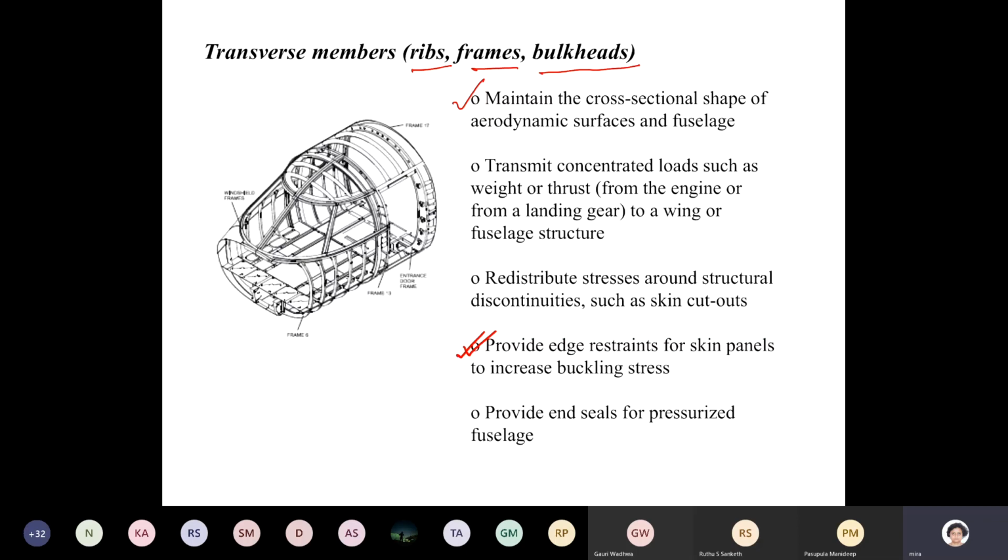That's what the bulkheads do. The mathematical part, the part that comes from stress analysis, will be done only at the end of the course when we talk about buckling. But you will be able to visualize that bulkheads are nothing but the two fixed ends of the Coke can. Those two ends resist the compression of the Coke can, and that's what bulkheads do. They resist the compression or the buckling of the fuselage. Does that answer your question to a certain extent? Yes, ma'am.